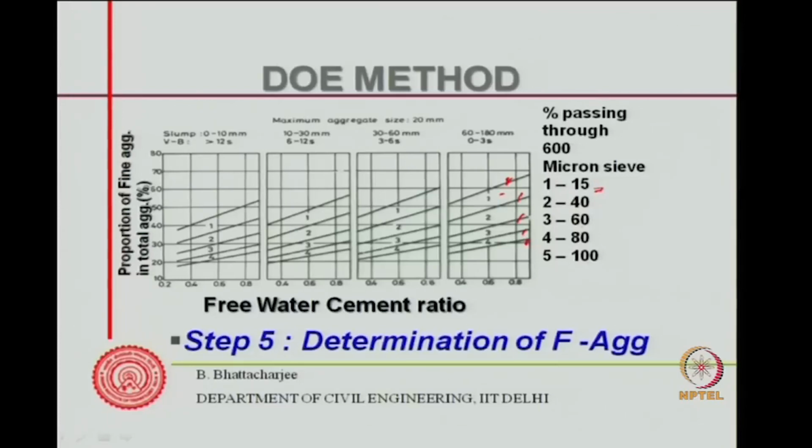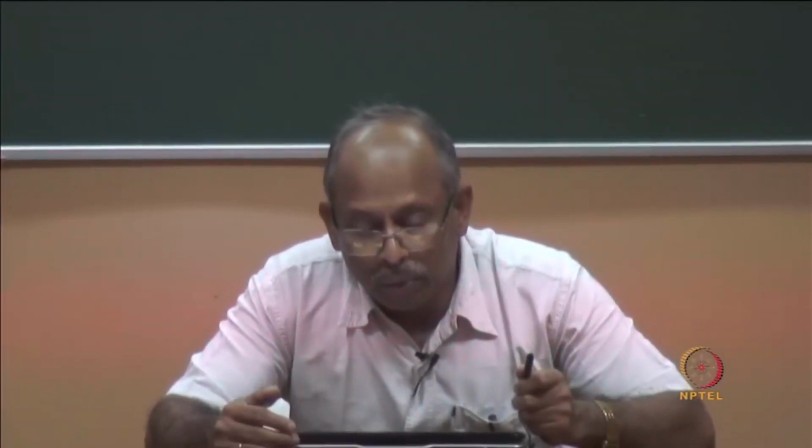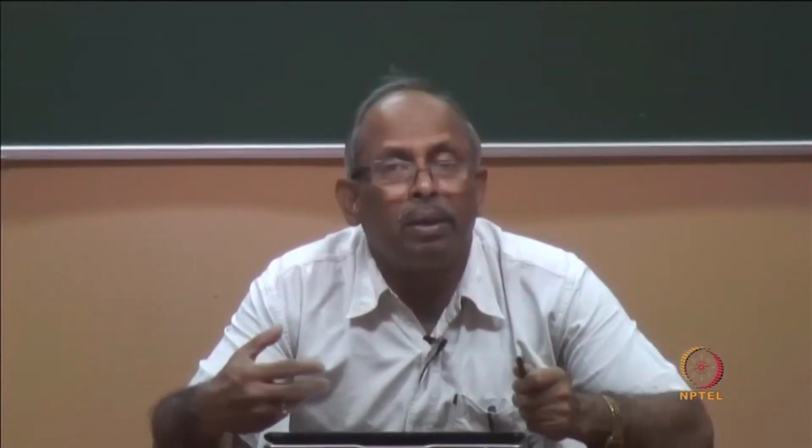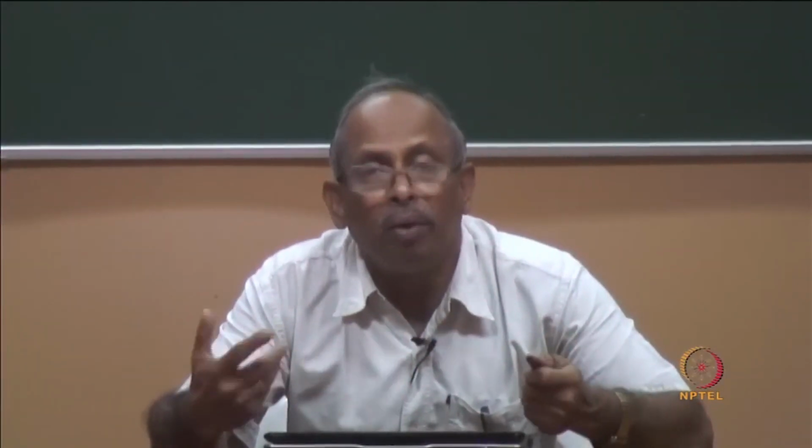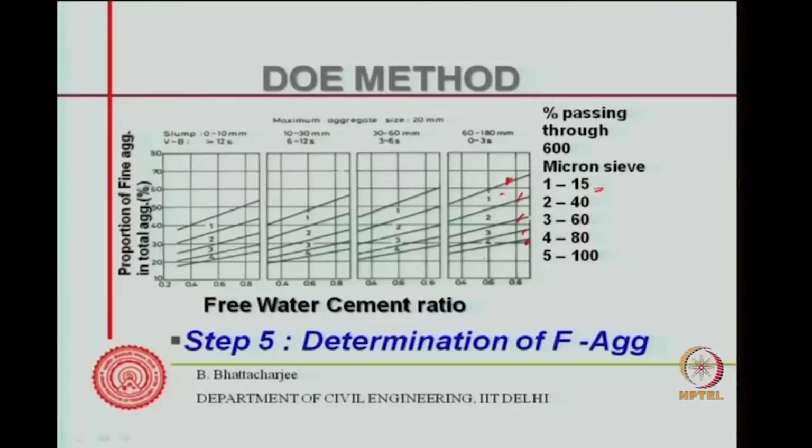So therefore fine content increases as we have coarse material in the system, because then coarse aggregate will reduce, fine content will increase. When fine is very fine, then you have got maximum amount of fine to use, and this also depends upon the slump. For a higher slump, you need more fines, lesser coarse aggregate. This is understandable, because as I told you, coarse aggregate don't contribute to moldability, right? It is the paste and then the mortar and their flowability that contribute to the workability.